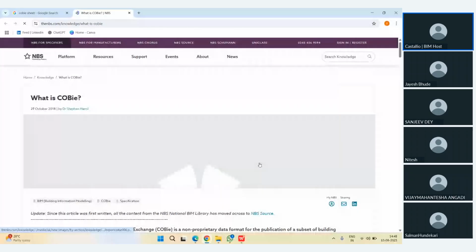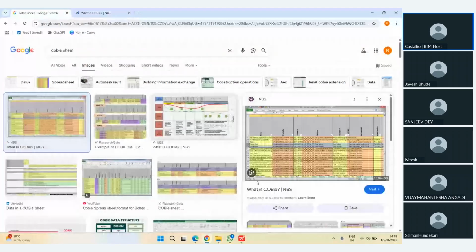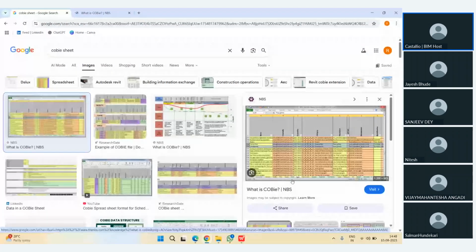It's not opening. You can see here the contact, facility, floor, space, zone, type, component, system, assembly, connection, spare, resource, job, impact, everything. Each and every detail about that particular component will be captured in the BIM model, and that has to be followed to generate the COBie data.